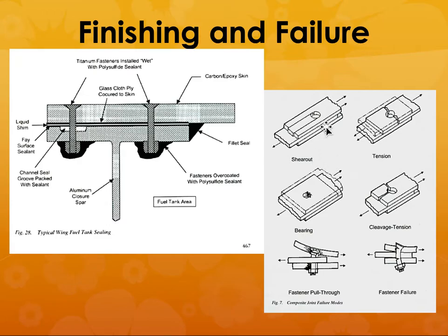So if it is going to fail, what happens? It will fail at this point. If it were not there, it would not fail there. Sometimes, it might even fail here. So part of it will get chipped off. So you have to go and repair the whole structure or throw away this structure and start with a brand new structure. So it's not a good thing from a manufacturing point of view.